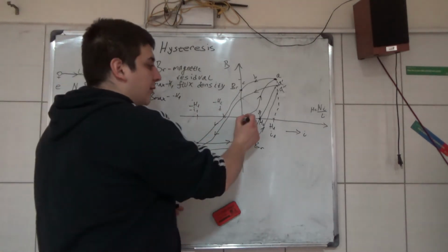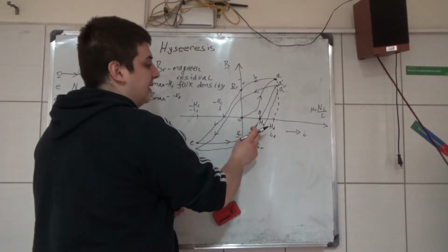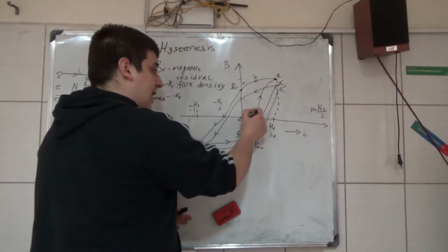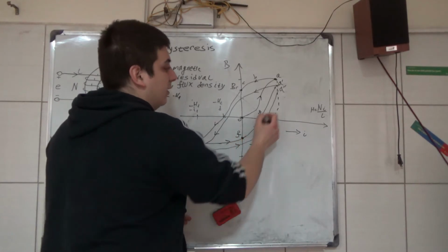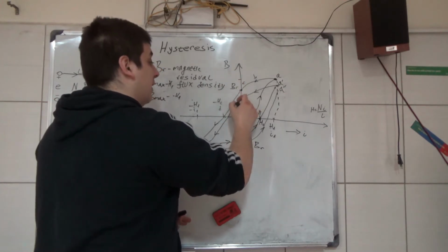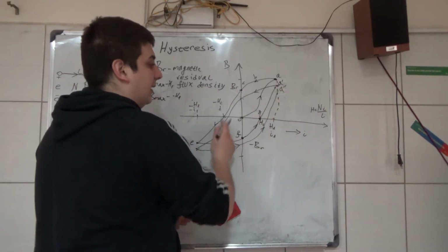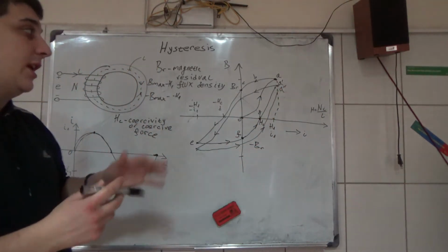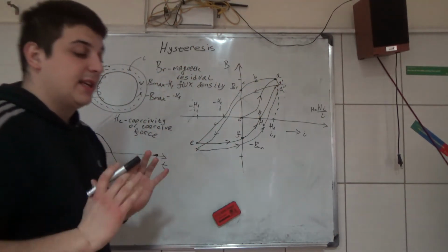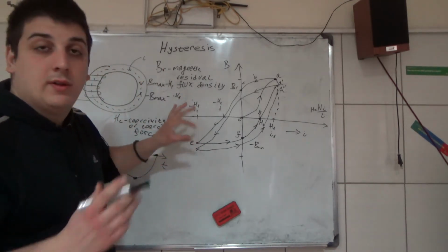It doesn't go here from 0 again, so this is a starting point, and then you will never have this magnetization curve again if it was magnetized. So it goes something like here to A prime, we have BR but a little smaller, it goes like this, and you will have this cycle, and eventually this will go to the same point after several cycles. This point will go together.